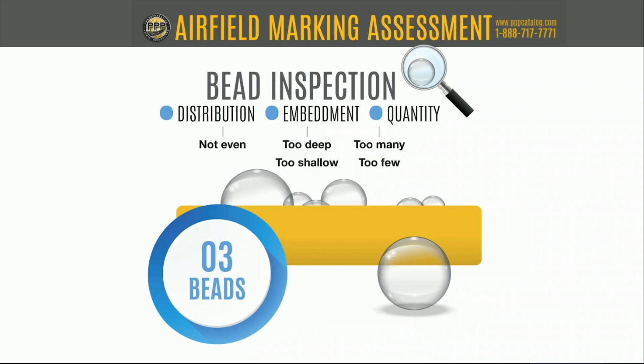Yeah, great. I'm glad you covered that because we see this in the roadway environment as well. We're talking about that 6,000 mile assessment we just did. When there was a problem, it was either there weren't any beads, there were too many beads, they were too shallow or too deep, or there was no marking there. That's a potential as well. But in most cases, even in the roadway environment, we find that it's beads.